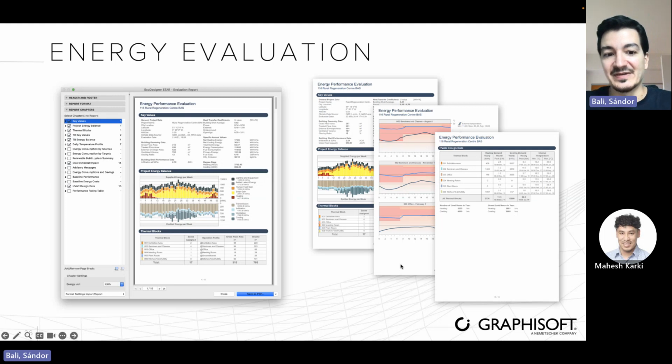But there are small things like this that you can also read from these diagrams as well. And basically, this is the most important part, the HVAC design data. So as I mentioned to you, we just said that we're not specifying our building systems. So basically everything that you have here as a heating demand, as a cooling demand for the hourly peaks in kilowatts, that is what the system will have to fulfill. So when in the next step we are going to define the building systems, we're going to use these values as the basis of the performance, right? And of course, then here we are going to use some rounding, because if you cannot buy, I don't know, maybe a furnace, 2.5 kilowatts performance, but you can only buy 5 kilowatts, then obviously you're going to say that the building system will be 5 kilowatts.